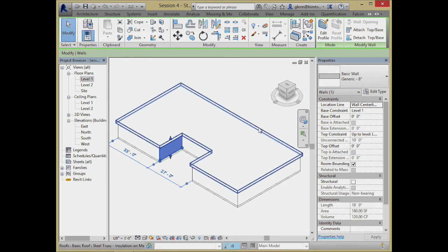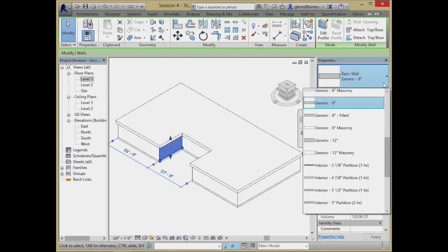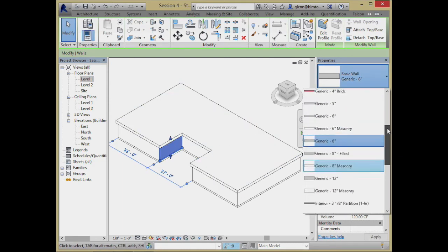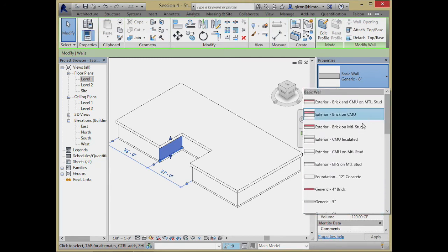If I look within these standard materials, the one that's probably closest to the exterior wall surfaces is EIFS. EIFS is almost like rigid foam that's covered with a layer of stucco. If you ever go up to a building that's being built, it'll often be covered with this yellow foam material, like rigid foam board, and it'll get stuccoed over. That's a system called EIFS. We could also put a wood wall up and cover it with stucco, but let's go with EIFS for now. That's okay.